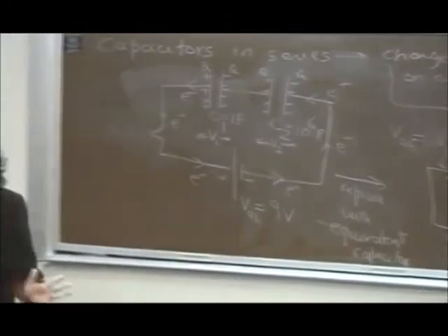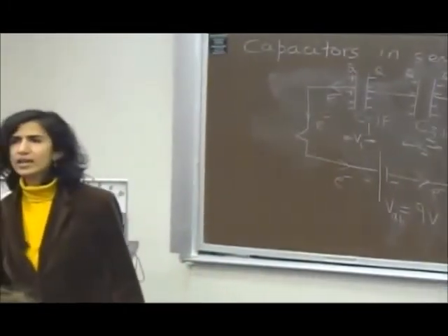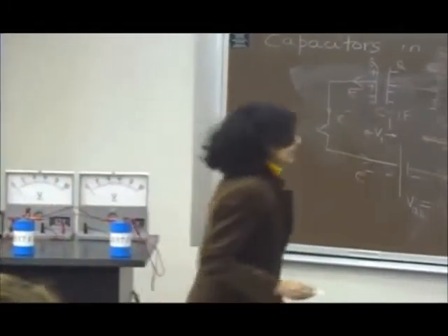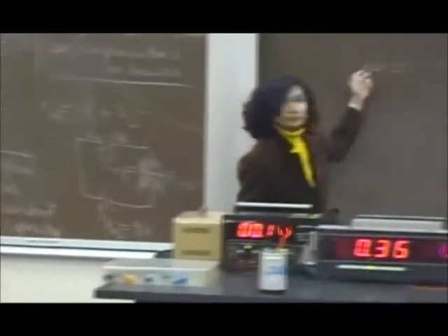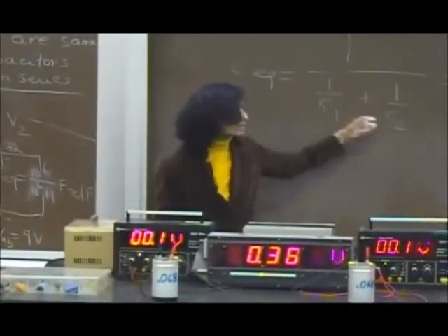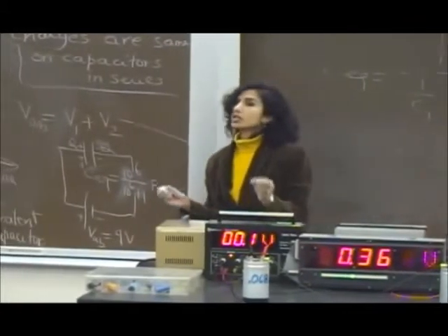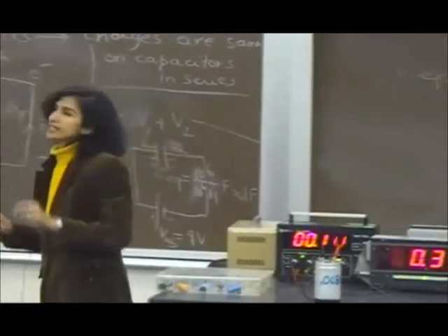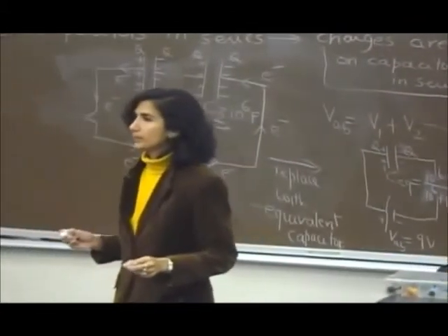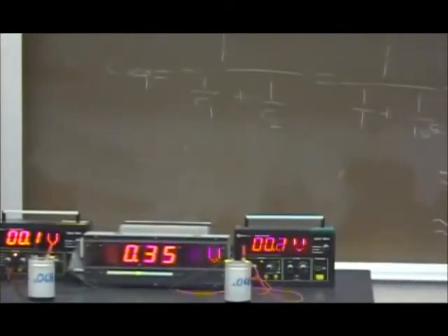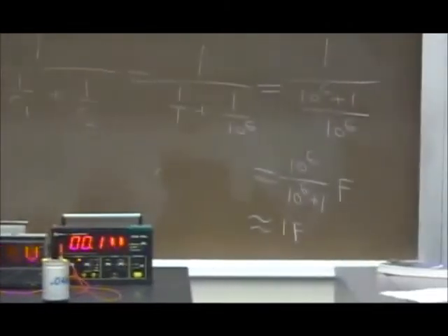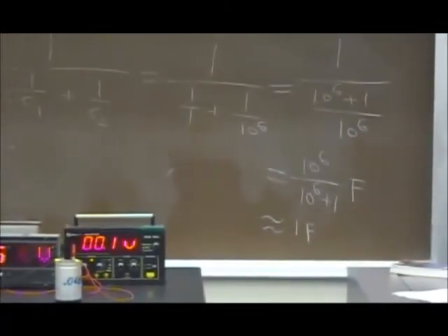One moral that you get from here already is that the equivalent capacitor for two capacitances in series is always smaller than the smallest capacitor. Do you see in this case, for example, each of them was 1 and their equivalent is half. Isn't half less than 1 and 1, both of them?